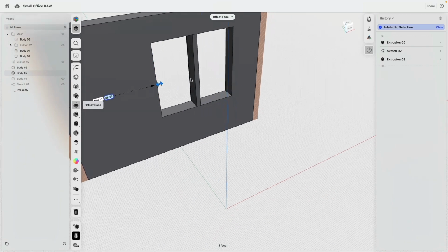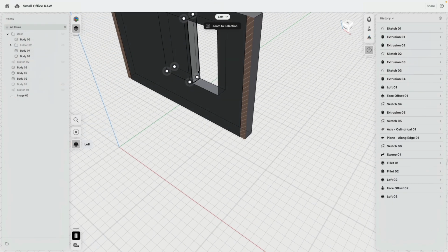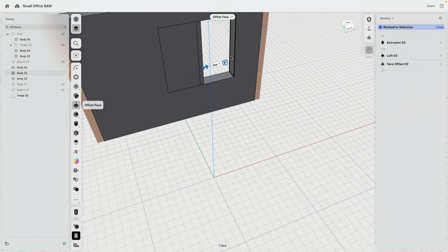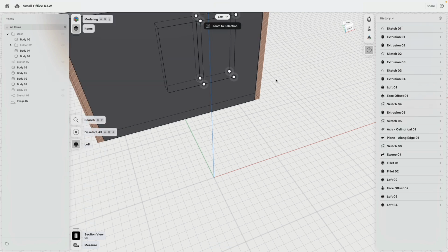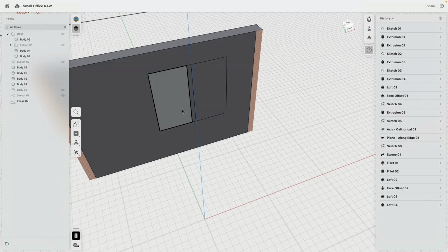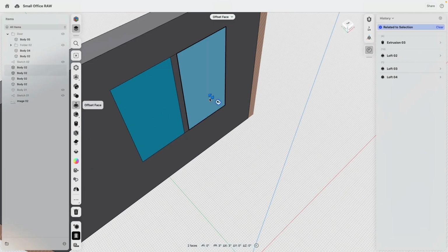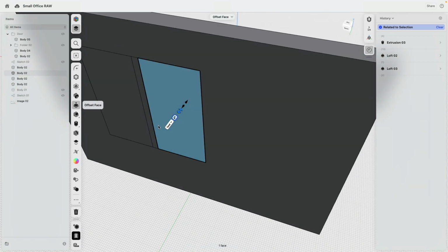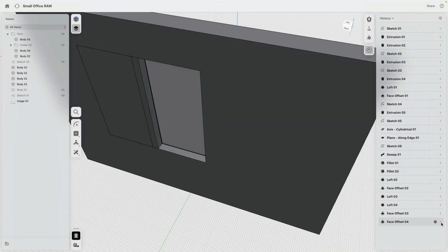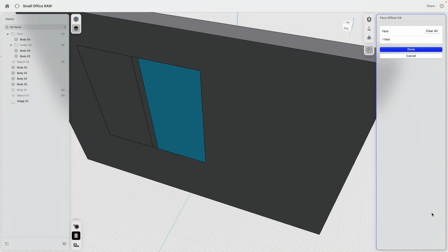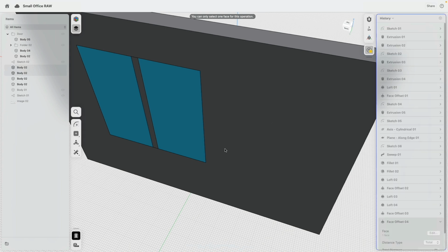To do the window now, look at this. I go here left and right, or I could also go up and down. Doesn't matter which way you do, but ideally select the same ways. This cannot be flush with the wall, so I move this back 3 inches, and then it's easy. If we select 1, that tells me 6 inches, and go 2 inches for material thickness, and then I say here, well, add this one too.